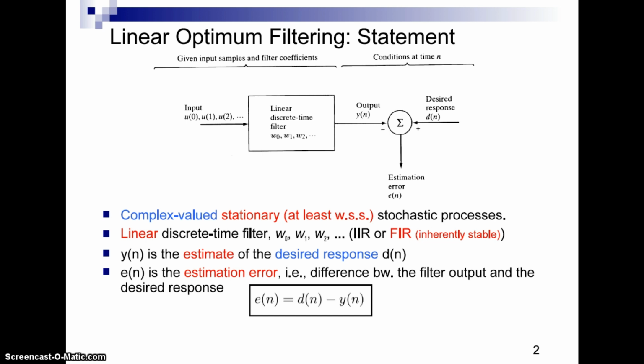Wiener filter theory is formulated for the general case of a complex-valued stochastic process, with the filter specified in terms of its impulse response. The reason for using complex-valued time series is that in many practical situations, like communications, radar, and sonar, the observables are measured in baseband form.